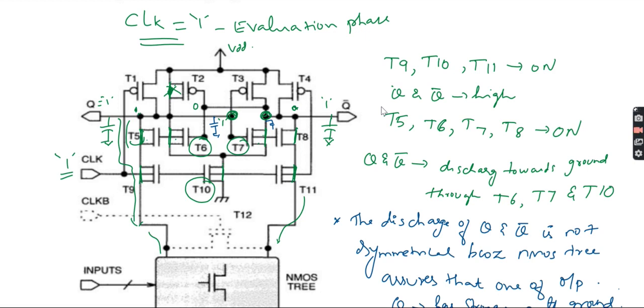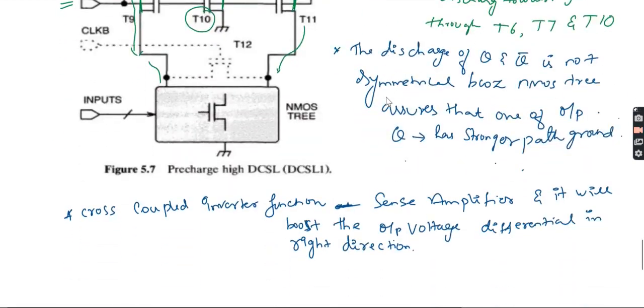In a rising node of Q bar, it is isolated from the NMOS evaluation tree. So this will limit the charge up of internal nodes. Wherever you are having the internal nodes, it will limit the charge in the NMOS tree actually. So it's like in DCVS circuits, where the NMOS pull down tree is never disconnected from the output actually.